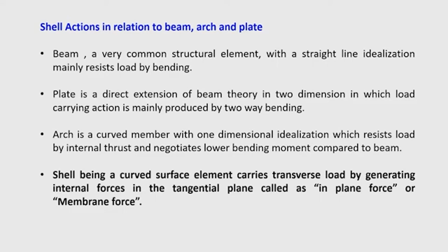Bending moment is minimum in the case of a shell, and it is seen that only when the shell joins a support, near the support the bending moment is predominant or significant, but away from the support the bending action is very negligible, and in that case the load is resisted by in-plane force or membrane force.